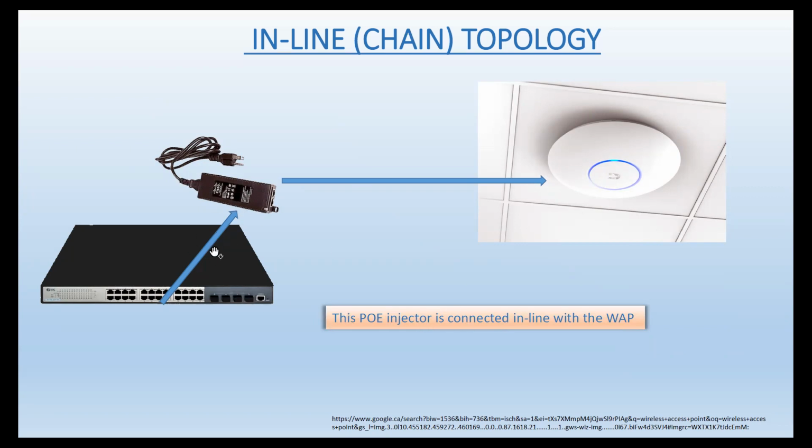That would go right in the equipment rack, right beside it. And usually there are all kinds of outlets there because things are being plugged in anyway, so power has to be available. You plug that right into the outlet to provide the power. And you plug the Ethernet cable into one of the ports here, and then from that, plug into there. So up to here is just a signal. The power is being injected on some of the pins and superimposed on the wire, so this cable carries the signal and the power. All you have to do is plug that in, and this device is being powered and is communicating. So PoE, power over Ethernet, those devices exist.